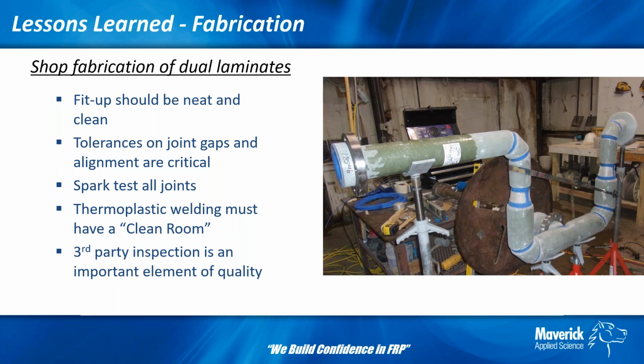And then specifically in dual laminate manufacturers' shops, you want to make sure that they're doing the thermoplastic welding work in a clean room. I've seen sometimes when the thermoplastic welding is sharing the same space as the FRP work, where they're grinding and you see dust everywhere from the FRP. Well, if that gets into your thermoplastic welds, it can contaminate the welds, and you're going to have a pinhole show up there or created from the first weld application. So you want to make sure that where they're doing the thermoplastic welding, it's a clean space, and to some extent environmentally controlled.